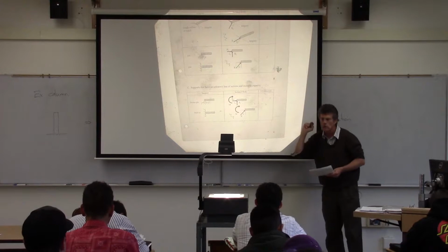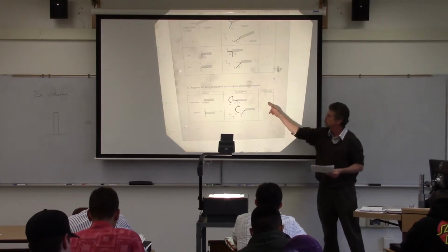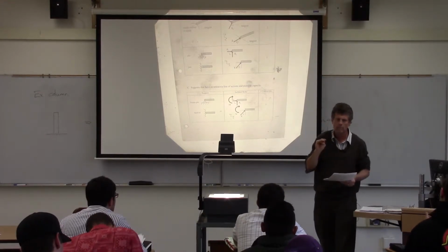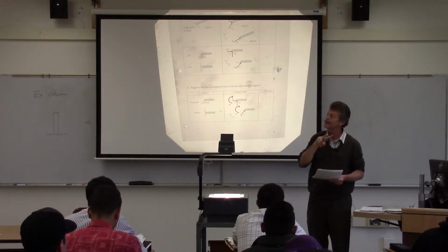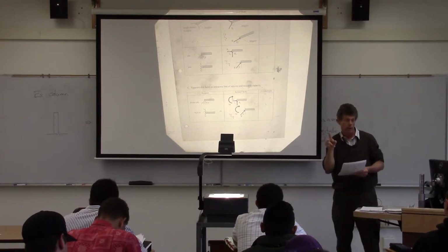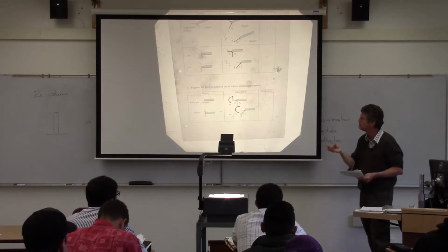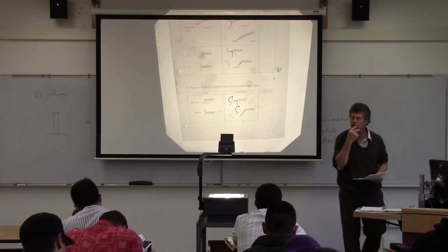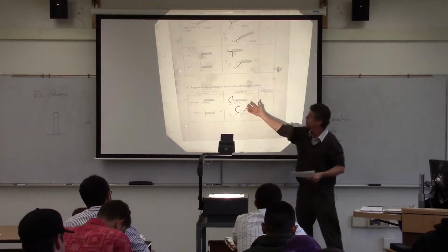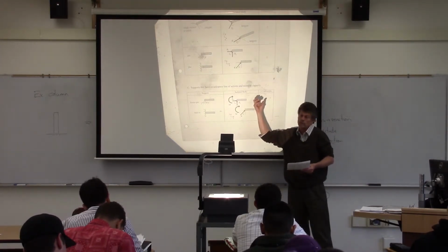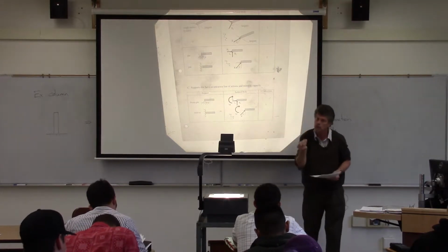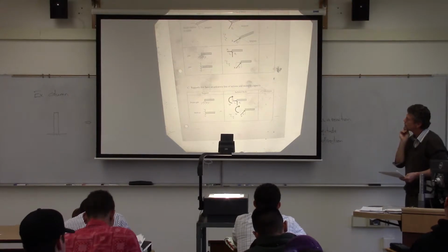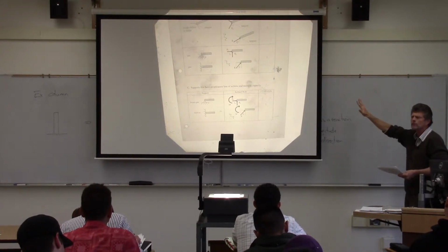Now, the key thing to note there is then there's three unknowns there. How many equations of equilibrium do I have in two dimensions? Three. We have the x, the y components of the resultant, and then the moment. So when we do this particular body, we have to be careful in the sense that when we isolate this or pull it away from the support, I have three unknowns, and I only have three equations of equilibrium. So I can't have a whole bunch of unknown forces there in that particular one. So I have to make sure that I've solved for other things along the way there.